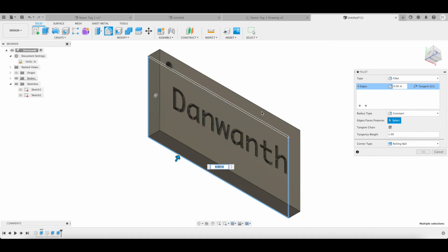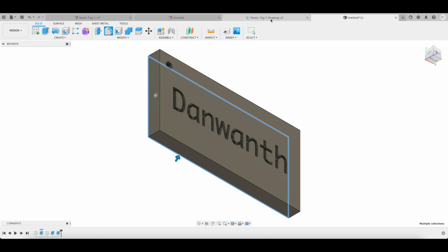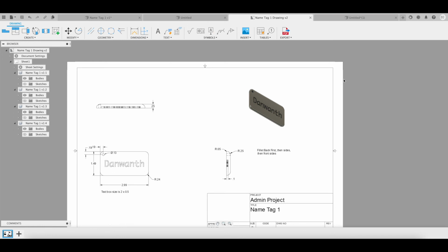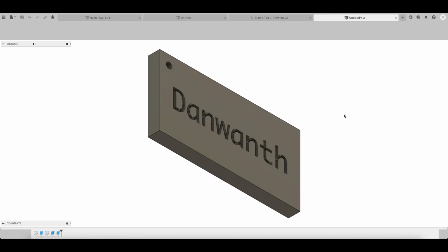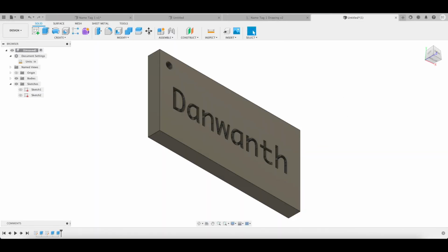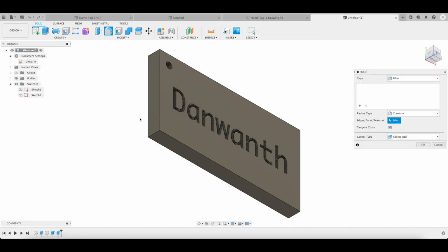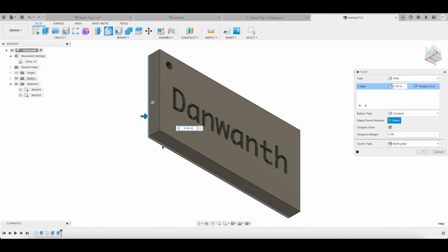So we want to fillet the back by, if I go back to my drawing, which we'll learn about how to use later, 0.25 inches. And let it load up. Oh, I have to go back to the fillet tool because... All right, I'm just going to select all my edges again, but you can fillet it by 0.25 inches by just entering in the value 0.25. We're going to select all 4 edges at once if I did not say that already.